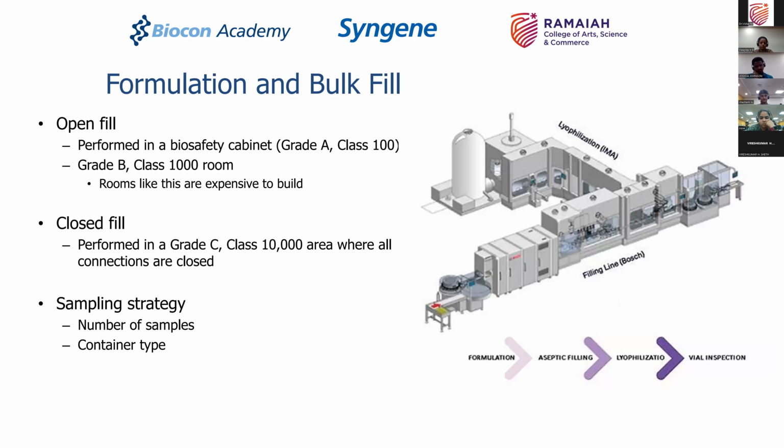The final one is, of course, you have now got the drug substance which is virally inactivated, filtered, ready. You will fill it in bags or you will fill it in containers. Those containers are then transferred to filling lines. And in a filling line, what happens is you know that you have to do a formulation, you have to do an aseptic filling. Why? Because you cannot sterilize the biopharmaceutical. If you try to sterilize a biopharmaceutical, you will denature the protein or the product of interest. So a biopharmaceutical fill finish operation is necessarily an aseptic fill finish process.